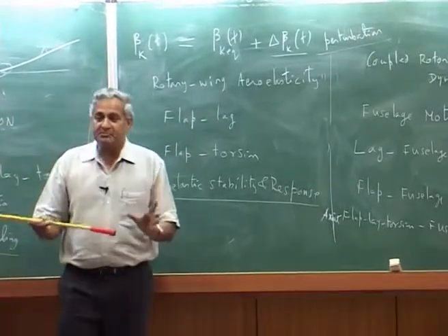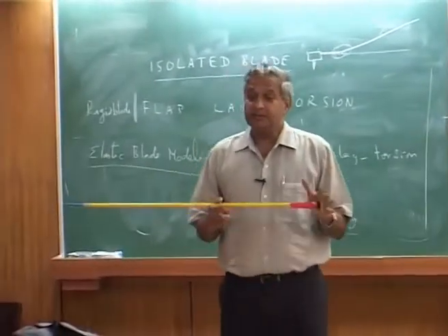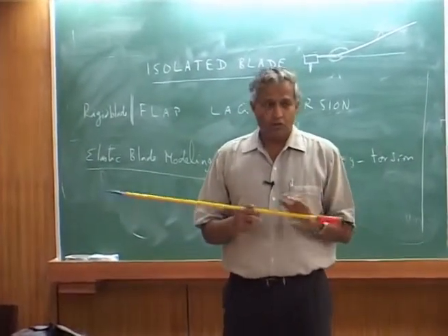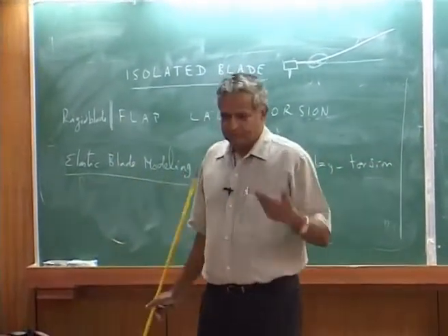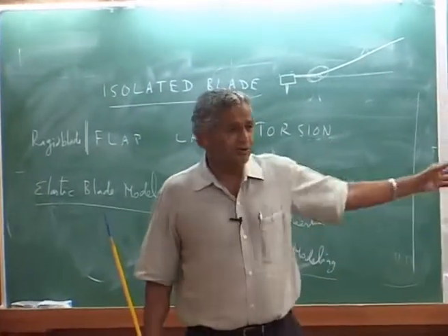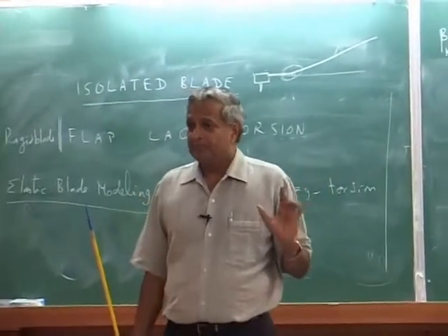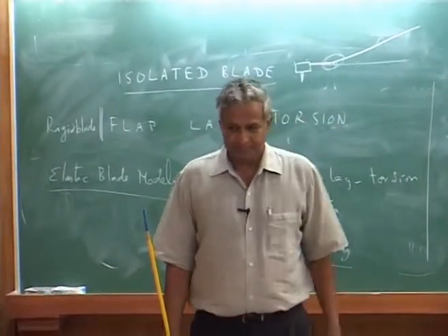You have to know perturbation analysis. So what is the perturbation analysis? You have developed your flap lag equations, assuming you know the inertial load, aerodynamic load and root spring model. You have developed coupled flap lag equations.